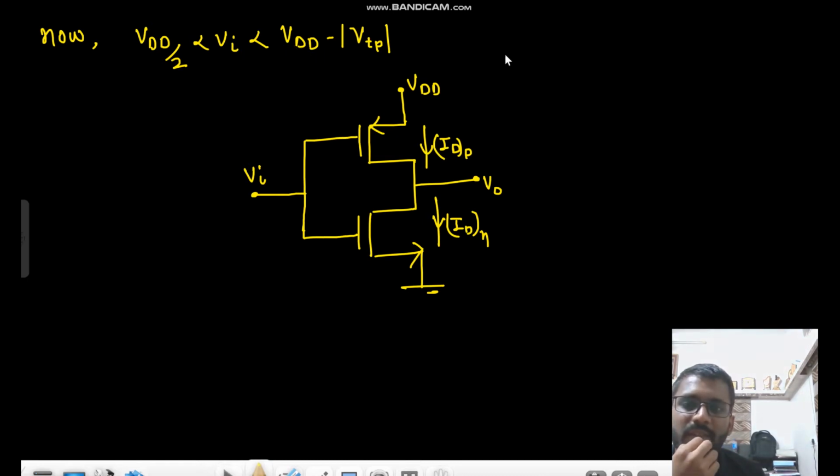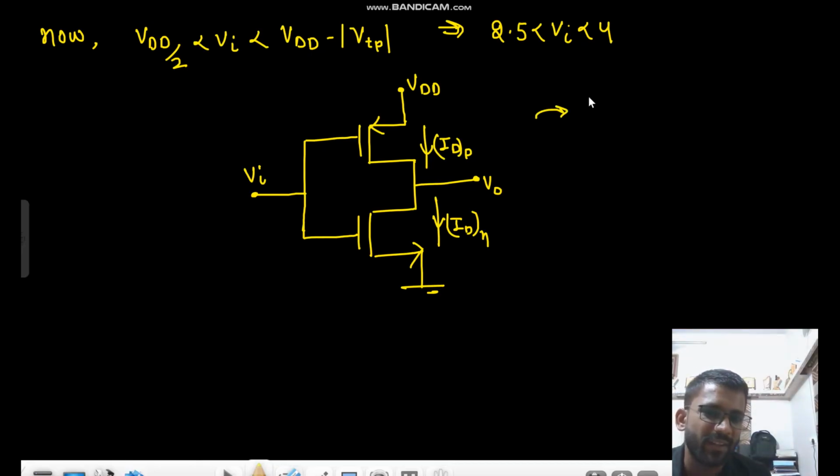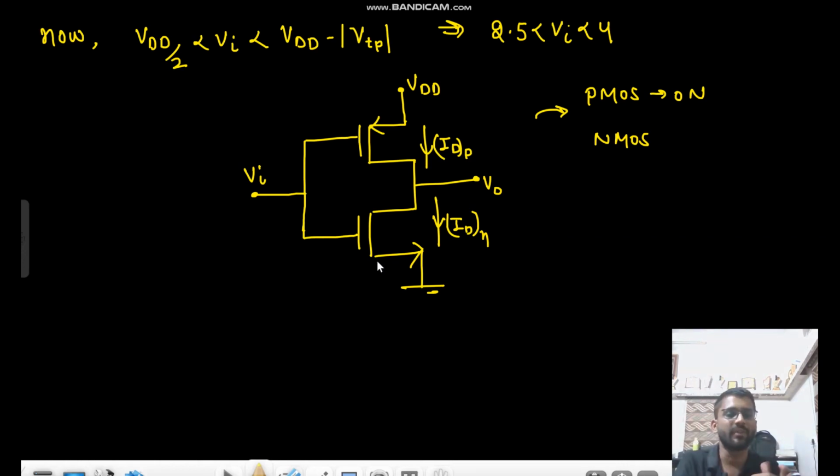So now your Vin is basically greater than 2.5 volt and less than 4 volts. So if it is less than 4 volts, this will be on, because 5 minus 4 will be greater than 1. 5 minus 3.9, it will be greater than 1. So here your PMOS is on, and also your NMOS. That means if it is greater than 0.7, it will be on. So it is less than 4, so your NMOS is also on.